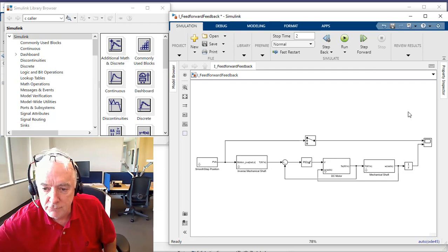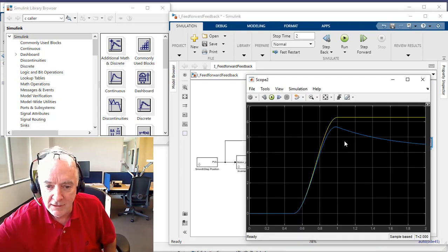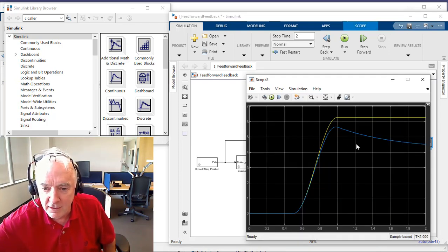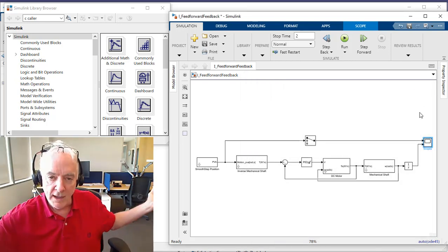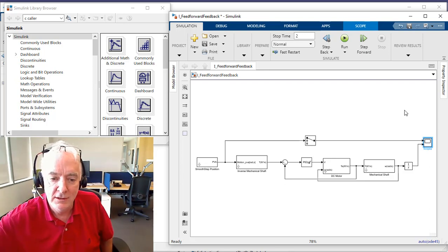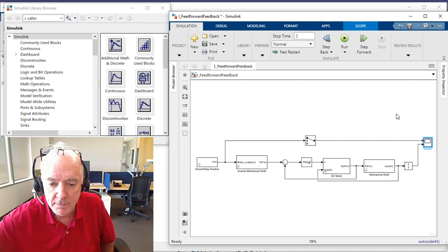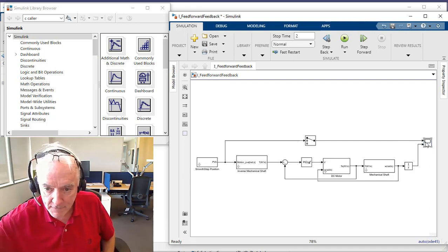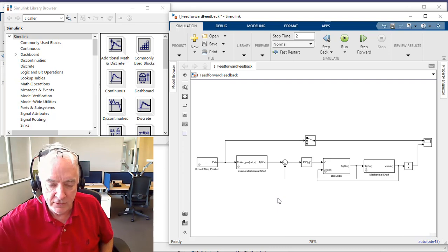Position, velocity, and acceleration are all expressed by what we're seeing as a difference right there. So think of our commanded motion, as interpreted through this feed forward controller, as what we want to happen, and it is combining very nicely to provide a very good estimate of what torque should be. Okay, but that is not the case right now.